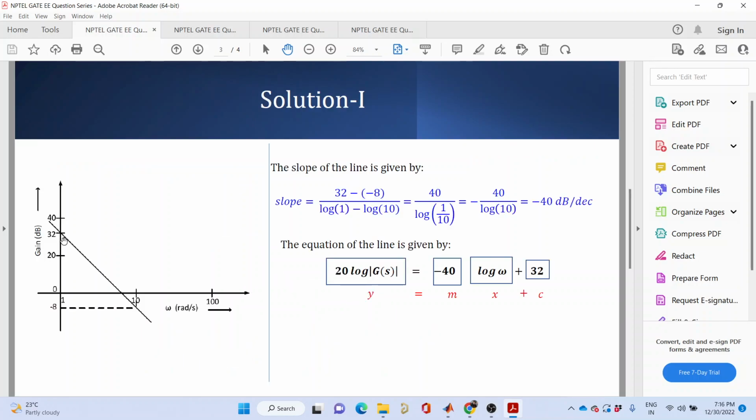So it is not that easy to plot the curve in a simple fashion. So this is one reason why we prefer a logarithmic scale. There are other reasons too. One, you have already told, you have to plot a large number of values in a small scale. That is another reason. There is another reason: if you look at any standard book, you'll see that they are taking each term, they are calculating the corner frequency, and near about the corner frequency, this asymptotic Bode plot holds true. And this concept I have explained in the previous session.